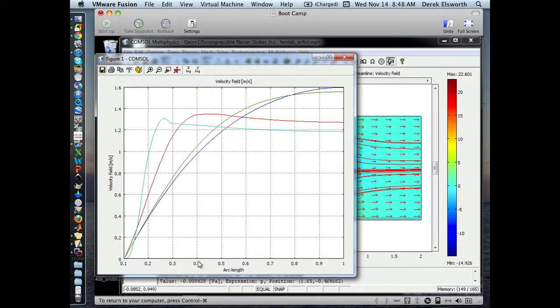As you go further upwards, vertically above it, you see a couple of different behaviors. First of all, this is the velocity versus distance. If you measure, this is the change in velocity with length away from the wing, so this is dv/dy in the viscosity term. You see that this term is 0 velocity at the wing, and it goes to the far field velocity. Actually, it should be equal to about 1, right? As you get further away, it's a bit larger than that. It shouldn't be.